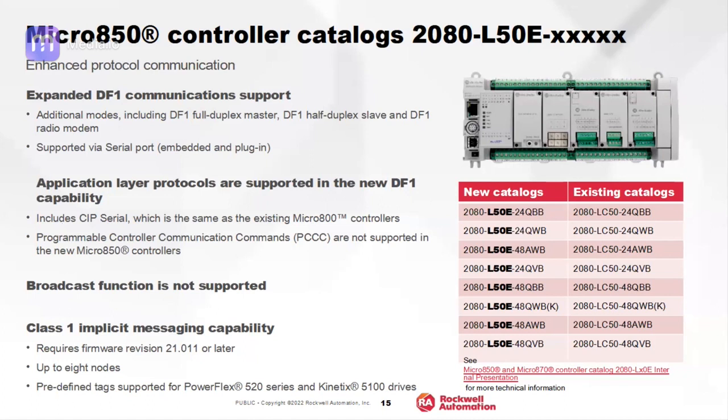If you want to use this controller with class 1 communication like RIO, yes, it can support 8 nodes maximum, after the firmware of revision 21.